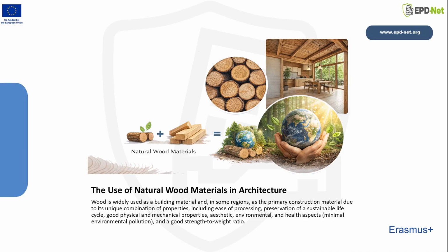Wood is widely used as a building material and, in some regions, as the primary construction material. Its architectural value comes from a unique combination of properties. It is easy to process, supports a sustainable life cycle, has good physical and mechanical qualities, provides aesthetic richness, creates healthy interior environments, and offers a favorable strength-to-weight ratio.